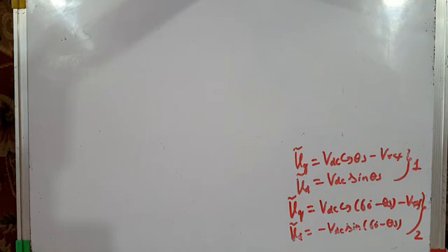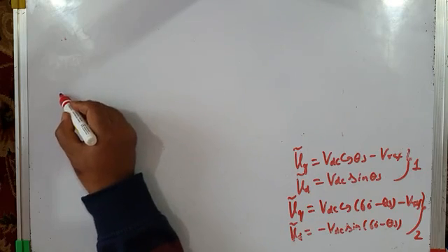Now, our aim is to find the stator flux ripple vector. We have a stator flux ripple. We will resolve it into D component and Q component, and we will find the D component stator flux ripple and Q component stator flux ripple. Okay, and that will give us an idea about a ripple in the current when a particular PWM technique is applied. Fine. So I will reproduce this diagram here.